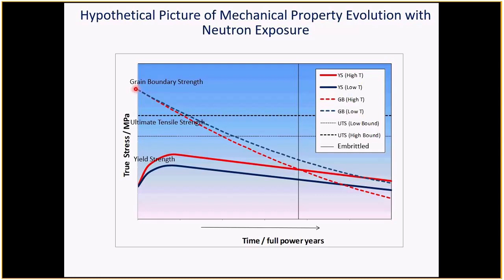And then this represents the grain boundary. So normally the grain boundary is the last thing where failure would happen. However, if the tensile strength, because of strain hardening, went up above this, eventually you may fail at the grain boundary, especially if you have those carbides on the boundary and this kind of thing. But let's not worry about that for now. Typically, the grain boundary has a higher strength than everything else. It's the last thing to fail. So if you didn't have carbides on the boundary, the boundary would be pretty strong.